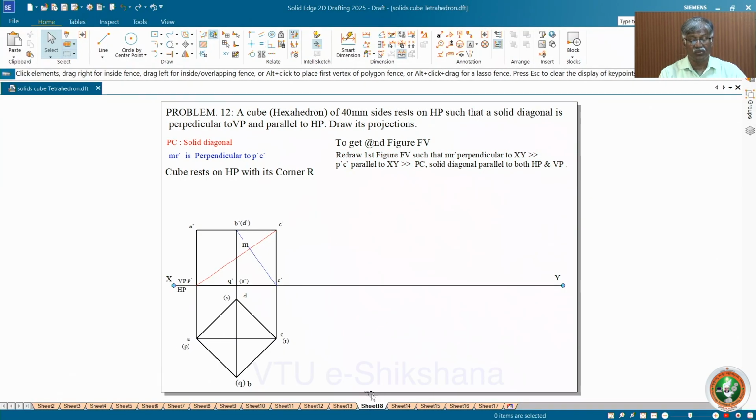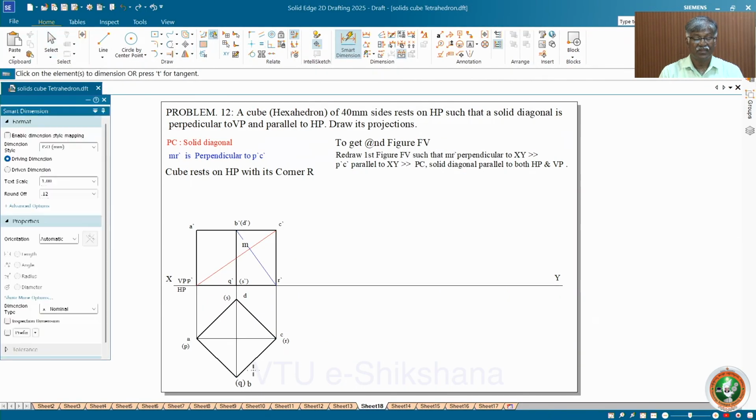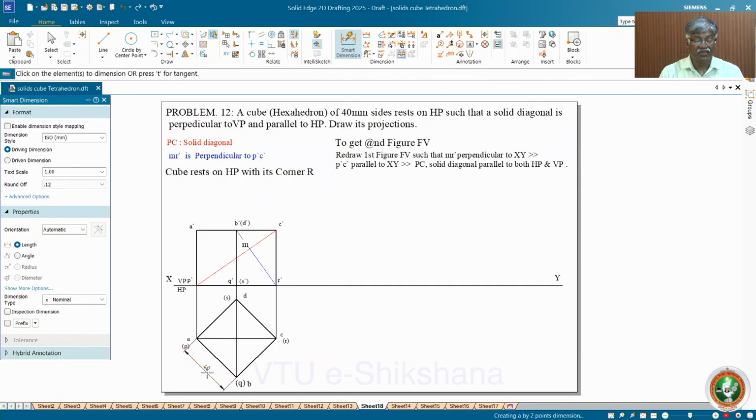In this position, what exactly you have to do is, now I will take this and show you how to do it. So I hope you know how to draw the corner condition of the square and then project it to a height equal to the height of the solid. Now check the validity. See, this is 40, height is also 40.